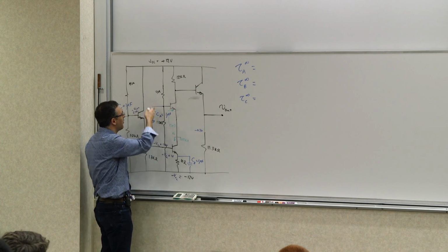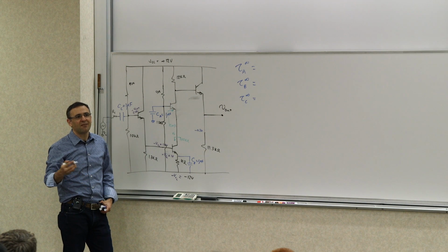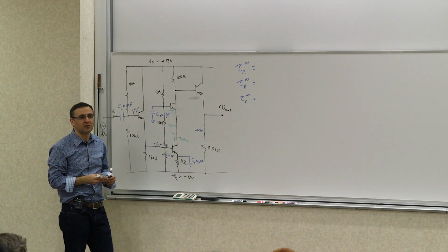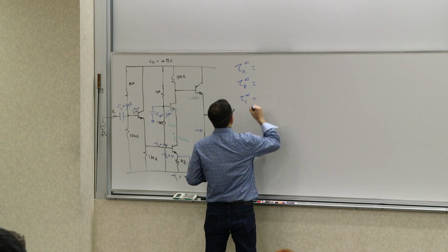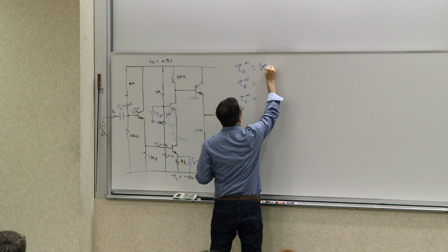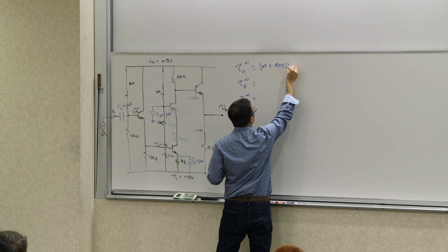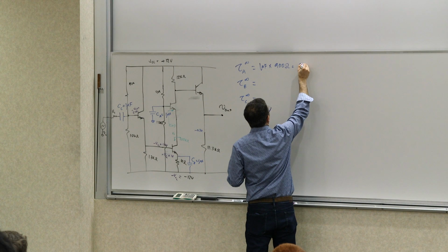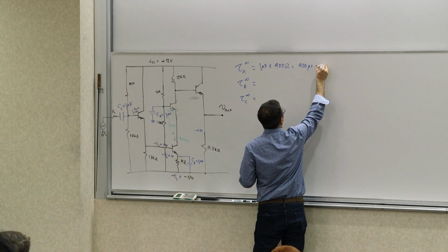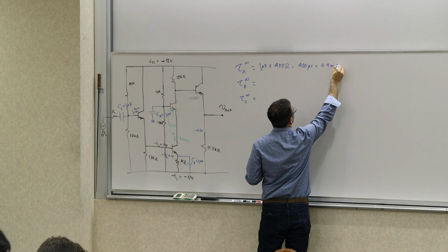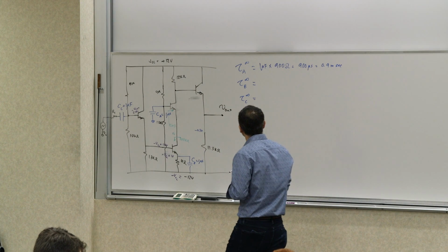It's 10 kilo ohm parallel 90 kilo ohm, right? So it's 9 divided by 10 kilo ohms, so it's basically 900 ohms. So that's 900 ohms times 1 microfarad. So it's 900 microseconds, or 0.9 milliseconds. That's one time constant, one infinite value time constant.